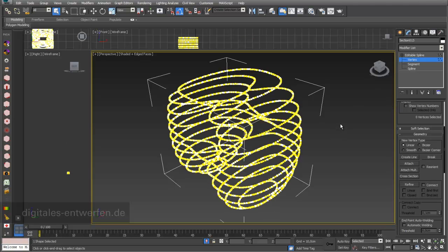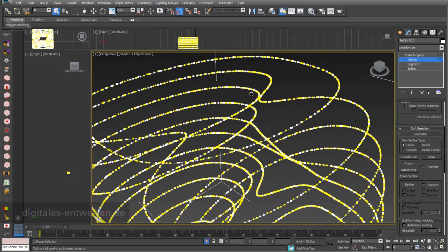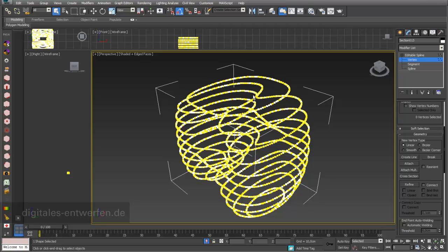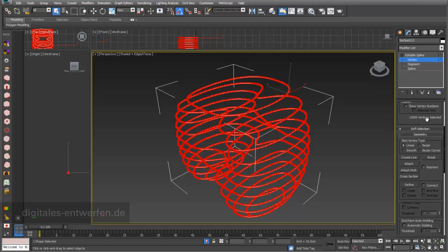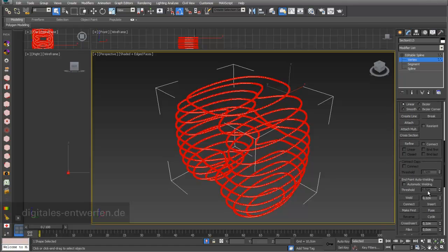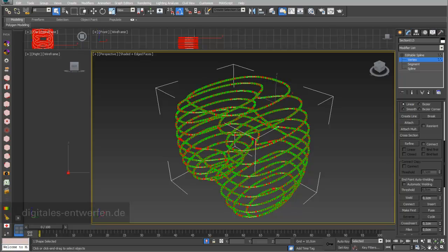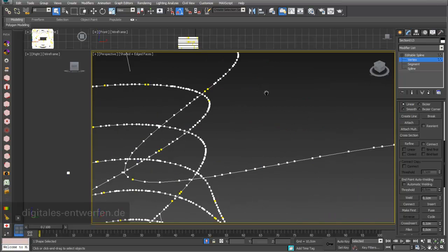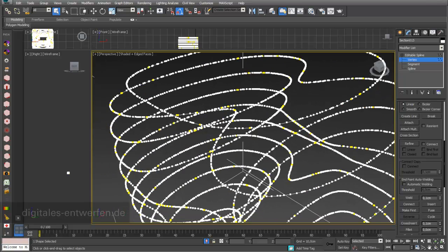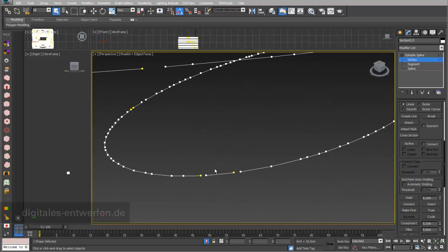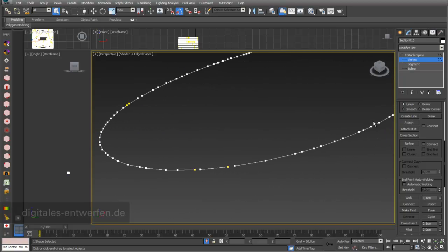And if I now go into my vertex area, I see a lot of yellow starting points in terms of splines, and I select all these little vertex points, 12,000 vertex points. Actually you can see it here in the menu, and select weld. Then it takes a while, on my computer, to be honest, more than 1 minute, and you can see that there are probably some few gaps. Here are some of these gaps. So the weld function didn't work so well.